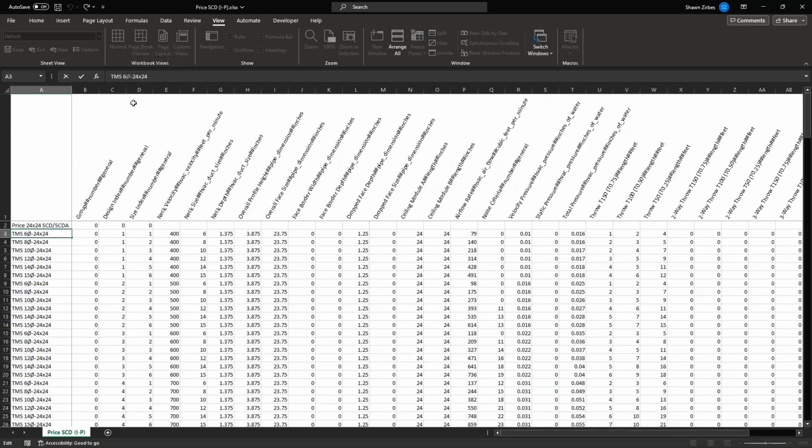So I'm going to steal this property here, by the way, copy that. This is going to be equals quote, SCD space quote. And then I'm going to put an and symbol, and for the next size, there's actually a property in here that's called out as next size. In fact, these are very logically named. They don't necessarily have to match up with the names of the parameters within Revit, but they're very logically named here that I can leverage to match up with directly what the manufacturer calls out in their cut sheet.